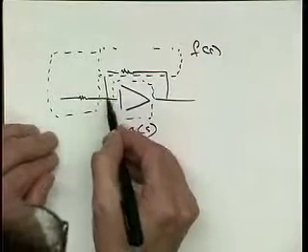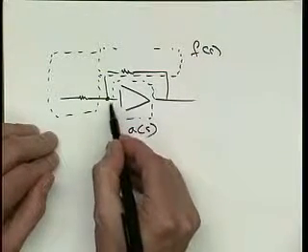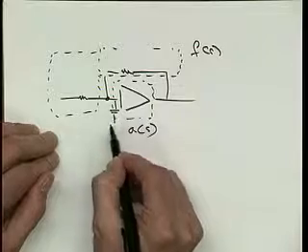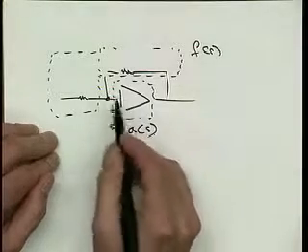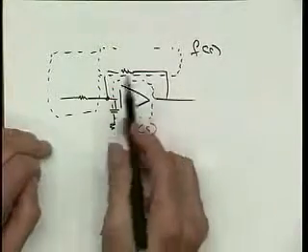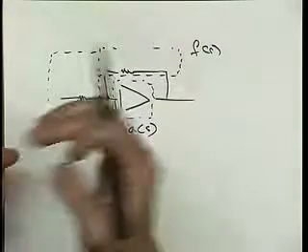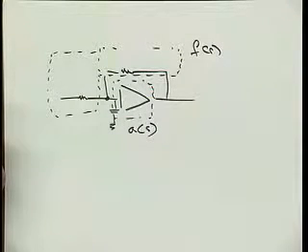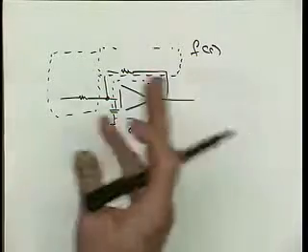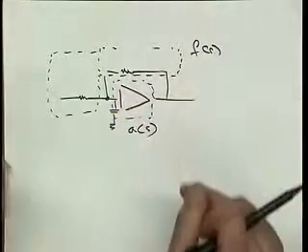And here you probably should, and rarely do, add the input capacitance of the amplifier at that node, because that could give you extra phase shift, and of course lower the phase margin of T of S, right? And if you did this in order to analyze stability, and we said that that's the number 1 reason why you do this exercise, well, then that wasn't such a good simplification.